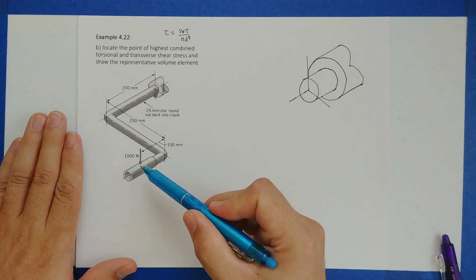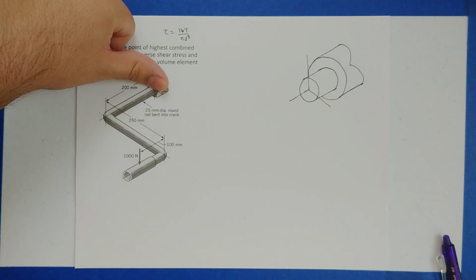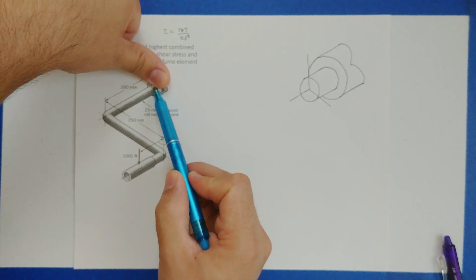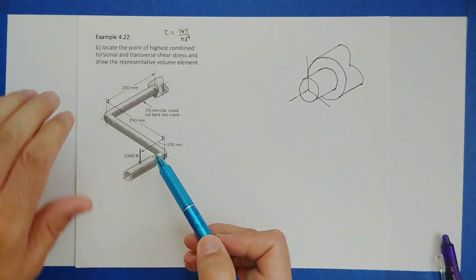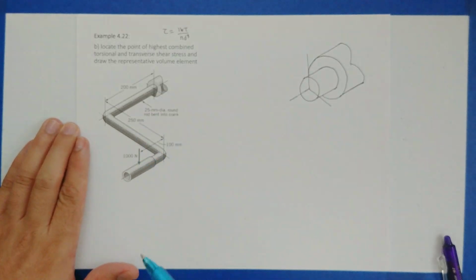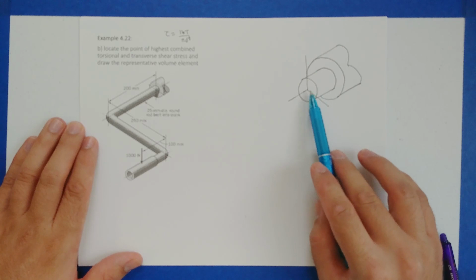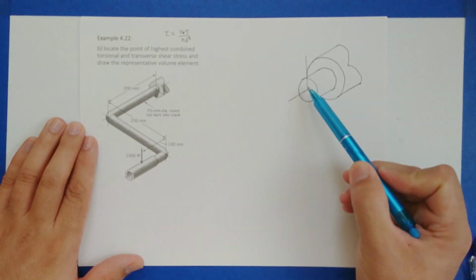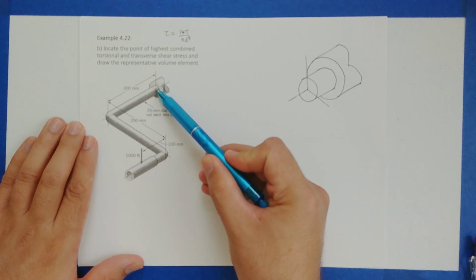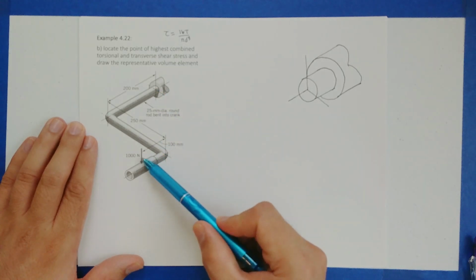Anyways, let's transfer this load over here. Again, I want to remind you, you could section over here and figure out the internal forces and moments to make this be in equilibrium. You'll see that those forces and moments should have the same magnitude, but opposite direction, of what I'm trying to get over here. So my shortcut is, instead of figuring out the reaction forces over here, I'm just going to calculate the resultant force and couple moment at this point due to this force.